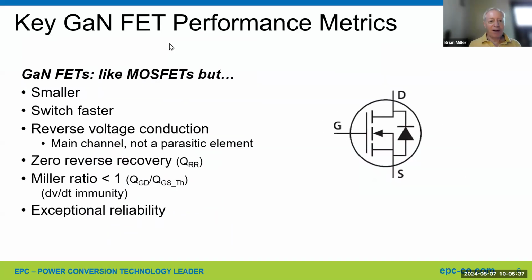Another introduction about GaN FETs. They're kind of like MOSFETs, except they're smaller. They switch faster, and that means they switch more efficiently. So you can switch them, and the transition time where power is lost is much shorter. They do have reverse voltage conduction.